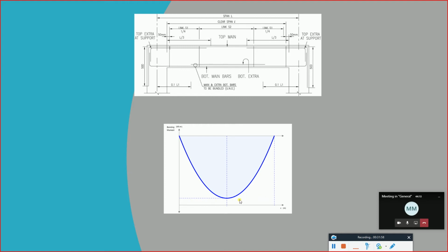If it's not sufficient in the area where the maximum bending moment is located, we need to add extra bottom reinforcement, for the distance of 0.8, which is the region affected by the maximum bending moment. The same thing goes for the top. We supply the top bending moment reinforcement. Even if there is no bending moment here, we supply top reinforcement for the connection between the beam and the column, even if the bending moment is zero.